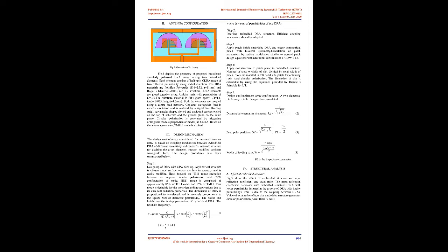In this paper, circular polarization is realized by generating orthogonal modes in CDRAs. A modified coplanar waveguide feed is considered since it reduces dispersion effects and radiation losses. A single element doesn't show a significant amount of gain, hence array design is selected.